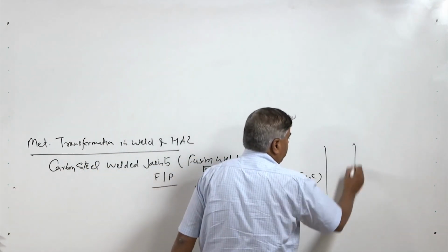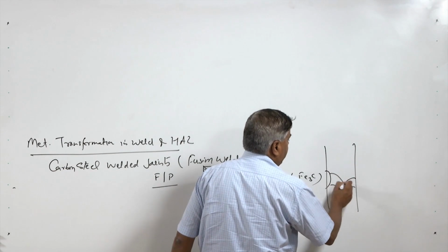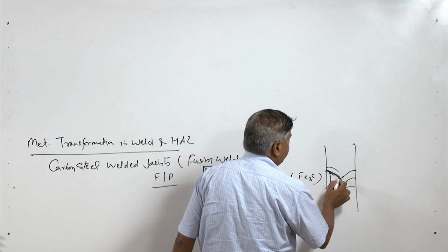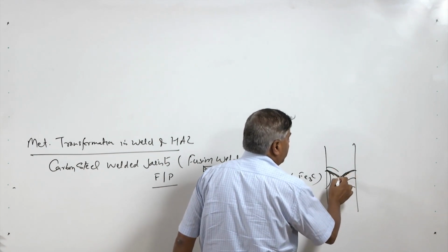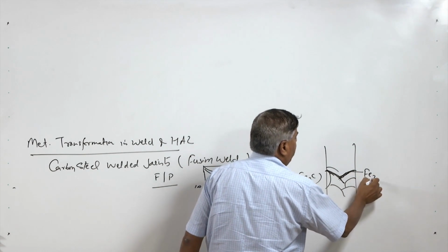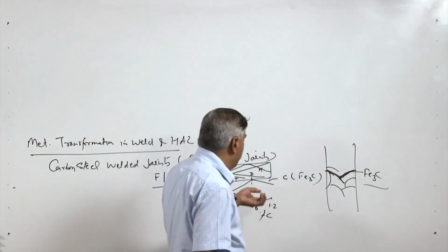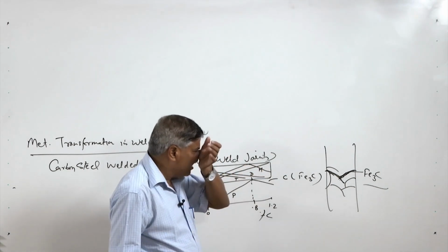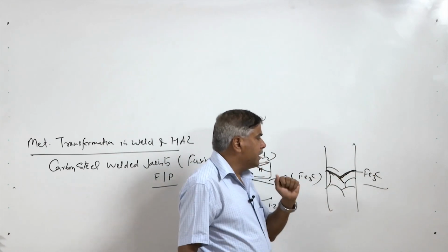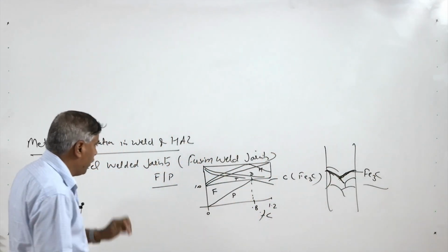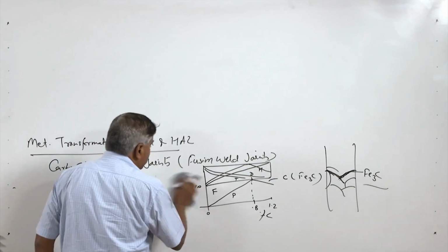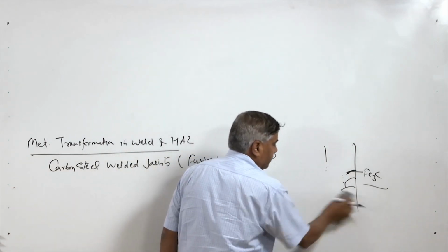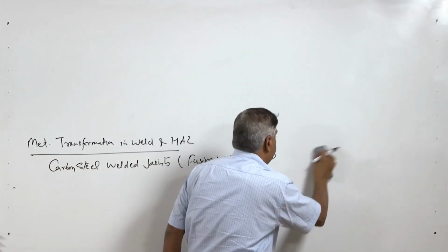So, say these are all the pearlite grains, and when the hard brittle phase starts appearing along the boundary, which is very weak in strength. When the Fe3C formation is in discrete form, the reduction in strength is not much, but the significant reduction in strength takes place when the continuous network of Fe3C is formed. So, basically with the change in carbon content, there is a significant change in the mechanical properties due to the changing proportion of the various phases which are being formed.